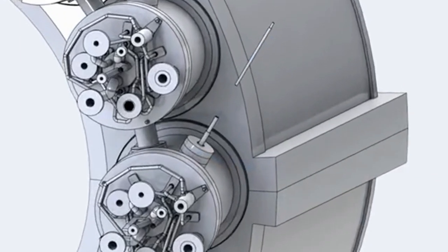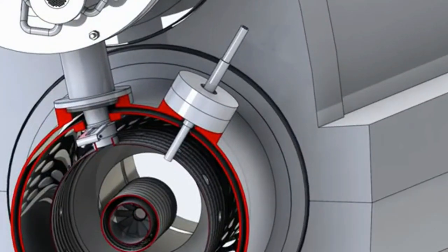On a DLN1 combustion system, spark plugs remain inside the liner throughout all the operation for startup and primary zone reignition functions. Once the flame is started on these chambers, it propagates to the other chambers through the crossfire tubes.